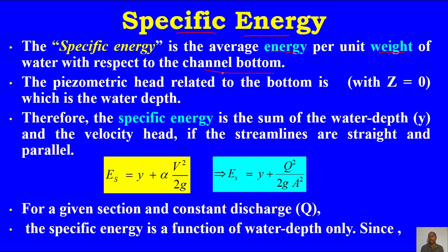With respect to datum, you have to include z, the elevation up to the bottom of the channel. So the piezometric head related to the bottom, with z equal to 0, is the water depth. Therefore, the specific energy is the sum of the water depth y plus the velocity head.